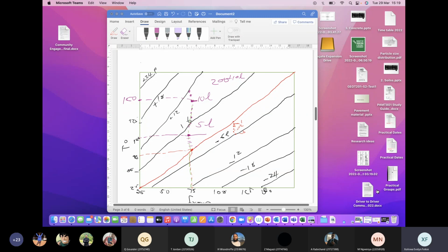And then they moved to 215. Remember, the 215 will be the water requirement because it was 210 plus 5. So you no longer have 210, but you have 210 plus 5. That's why they have 215 divided by the water to cement ratio. And then the other ones, you apply the formulas to get the values that you need to determine.